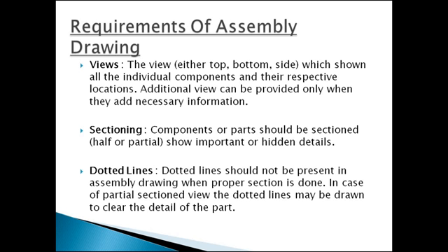Sometimes front view, top view along with the side view, right hand side view, left hand side view. Sometimes only the right hand side view is required, sometimes only the left hand side view is required, and sometimes both side views are required. If the component is symmetrical, then only one side view is sufficient. If the component is not symmetrical, then both the right hand side view and left hand side view are required.